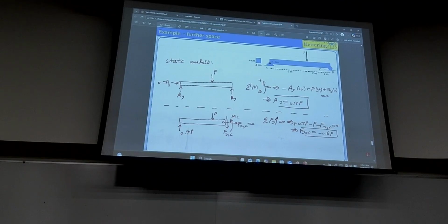All right, Evan, I see that you're ready. We are now interested in MC. How would you go about it? Remember, we still have three equations in statics: sum of forces in X, Y, and sum of moments. Sum of forces in X, would it help? No. It gave us Fx equals 0 already. Sum of forces in Y, we already used it, so one is left.